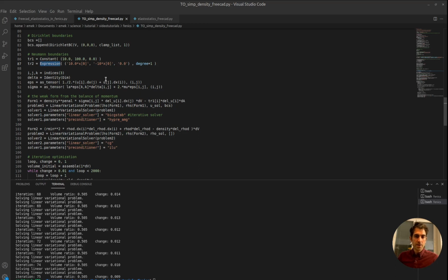So there are some benefits. If you have full control by using the code, you can immediately do more difficult stuff. And also if you want to use a more sophisticated material equation, which we don't do here, we just do linear elasticity. But if you want hyperelasticity or something like that, then it is also rather simple to put it into the code once you understand how it is working. But mostly the biggest part of it, if you have a larger system and need a lot of computing power, is that the choice of solver will be really beneficial to have control over.